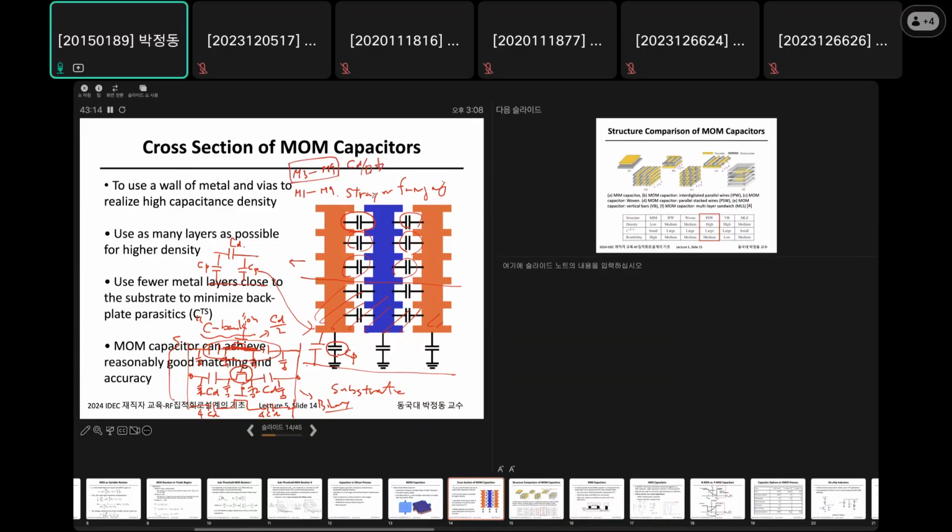Density will be reduced, but if you implement a capacitor bank with a high CP, then you will lose your controllability, okay? So whenever you try to design any capacitor bank, do not try to use M1 and M2 at least. Sometimes I remove M3 as well, okay? Remove it to reduce this CP.